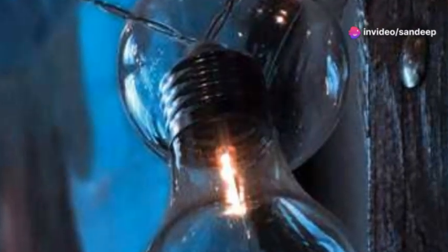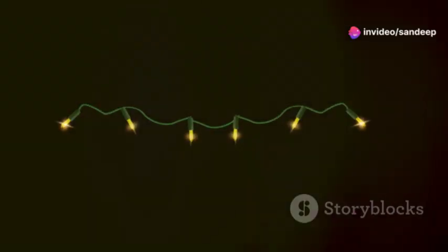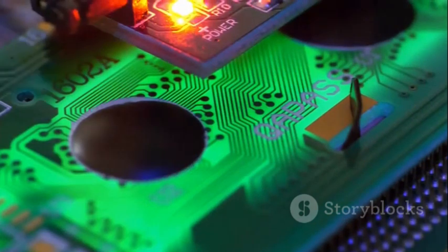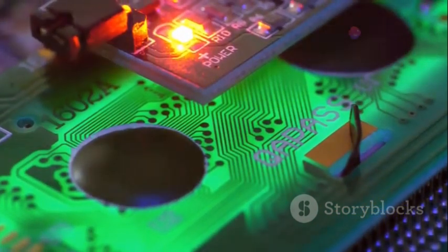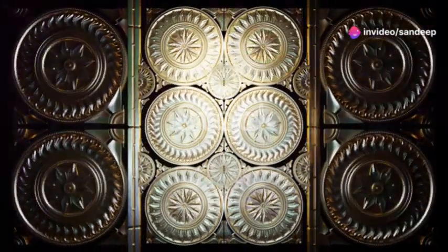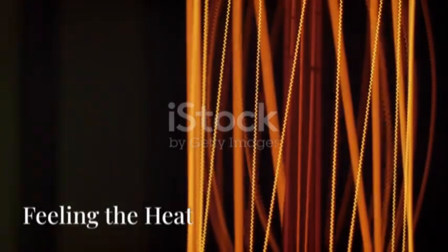If one bulb burns out, the rest stay lit. That's because they're connected in parallel. Each bulb has its own separate path back to the source. In a parallel circuit, the components are connected across each other, creating multiple pathways for current to flow. The voltage across each component is the same, but the current through each component can be different, depending on its resistance.